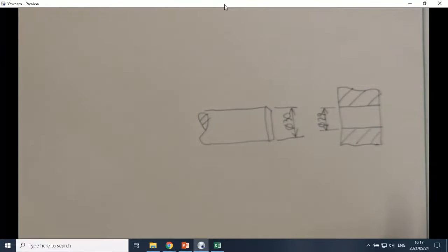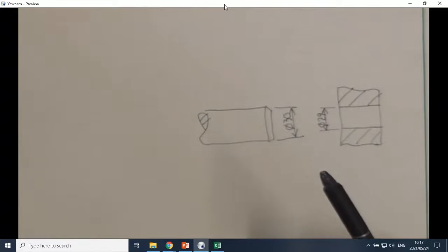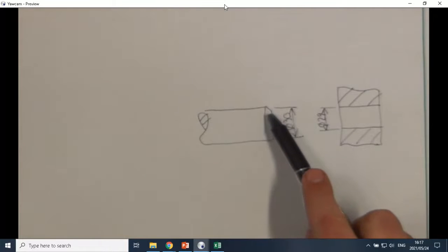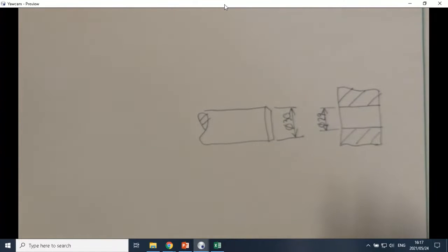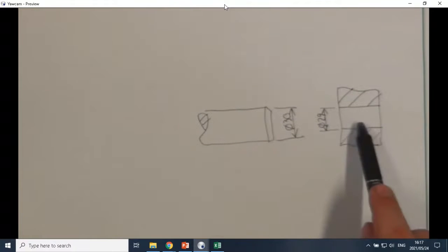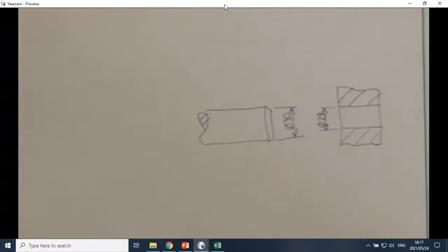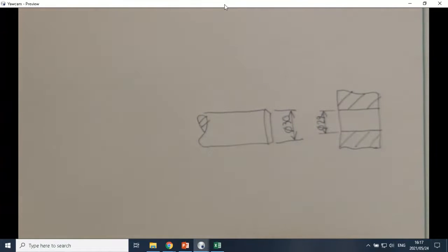Remember, we are assuming most of these components are metal. So this is not even an interference fit. Remember, with interference fits, the decimal value that this one is bigger than that one is literally like 50 micrometers, not a whole millimeter. So a 30 shaft will never fit into a 29 hole. So when trying to assemble your stuff, look if the dimensions actually make sense. If it was a 30 shaft and a 30 hole, then yes, it could fit, but not with a 29.